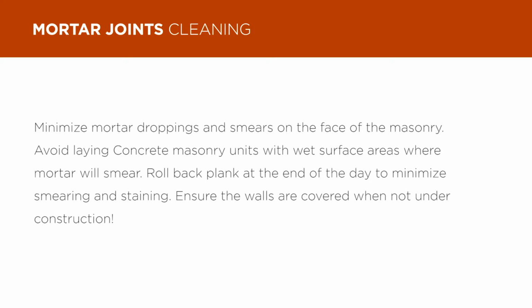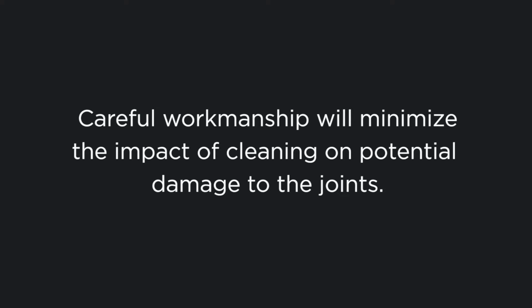Minimize mortar droppings and smears on the face of the masonry. Avoid laying concrete masonry units with wet surface areas where mortar will smear. Roll back plank at the end of the day to minimize smearing and staining. Ensure the walls are covered when not under construction. Careful workmanship will minimize the impact of cleaning on potential damage to the joints.